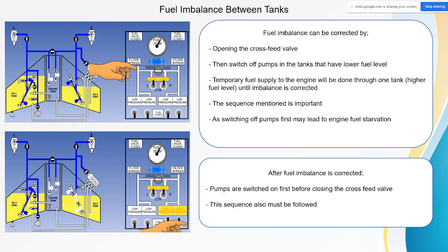Okay, sir. That's why don't worry. Normally the aircraft for shorter routes, like here to KL and like BKI to Tawau, Lahad Datu, don't take much fuel. Even though the maximum fuel they can take is 15,000, they maybe take 5,000 only. So they are within the landing weight limit and they no need to dump fuel.